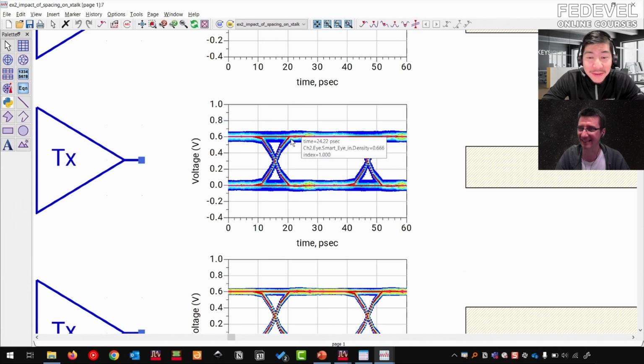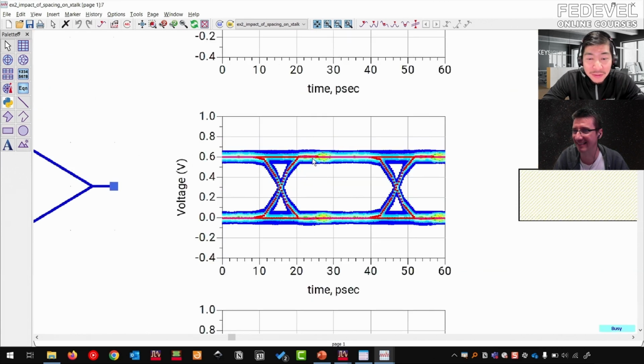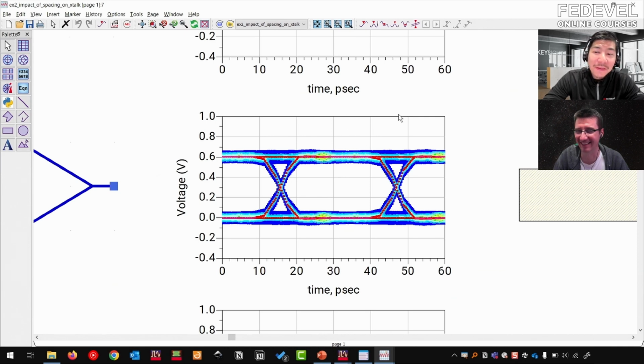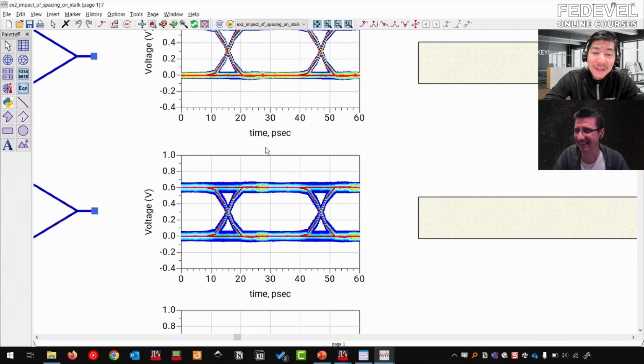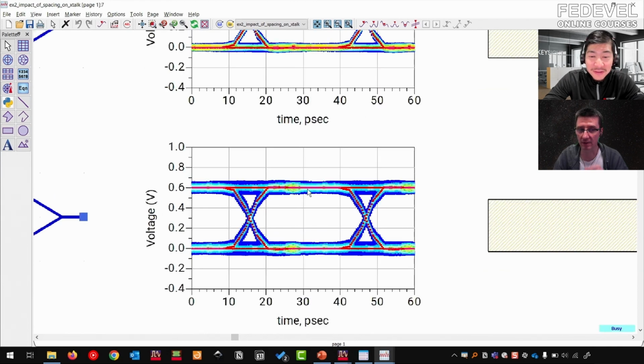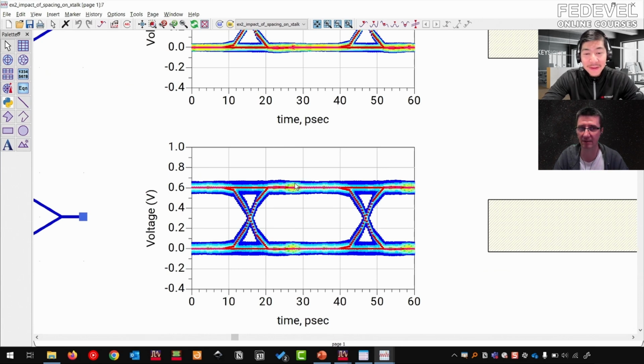Let me ask. The red I've created here is the ideal. Now we will see the blue. What we simulated is a little thicker than the red. Give me an idea what that could be. We talked about this term. I don't know. It's some kind of crosstalk. It's the near end crosstalk. Yeah, this is the signature of the near end crosstalk. Oh, because the near end crosstalk is wider? Yeah, it would make the eye look thicker, the different levels look thicker. So that's the signature for the near end crosstalk.